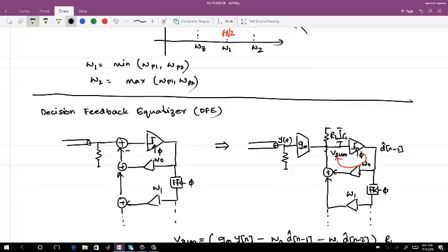Then as soon as it gives the output, that current is being summed up in the VSUM node. And that summing up node, that settling is decided by RLCL, where the time constant should be like T bit period by 3 for a 95% settling or something. And then that value should be ready a setup time, delta setup time, before the clock edge comes.